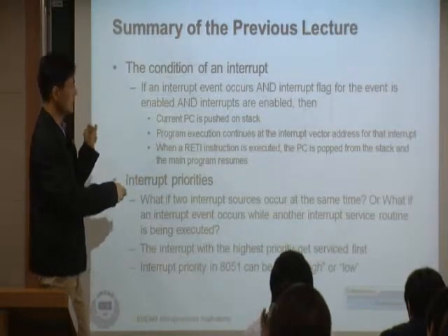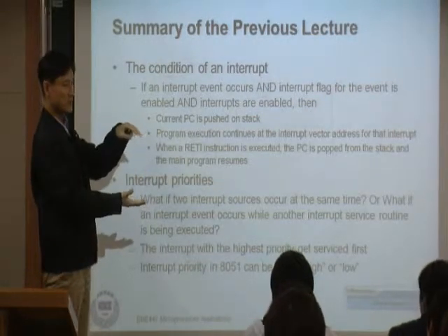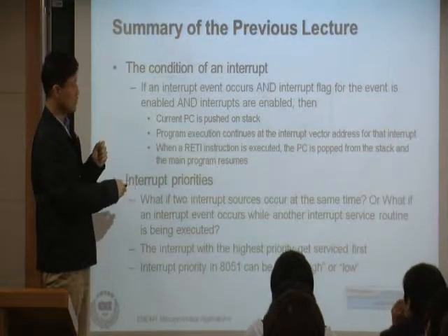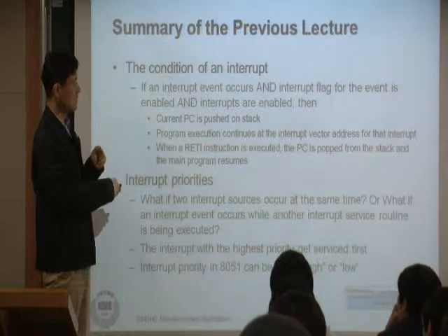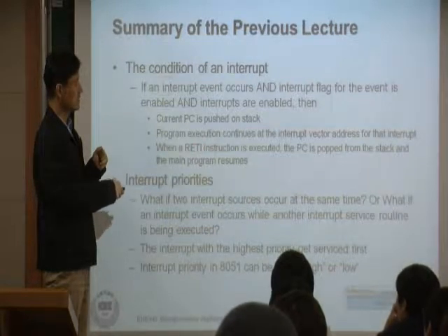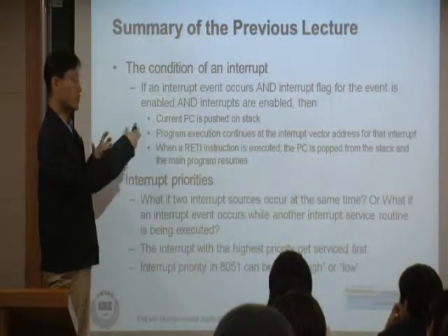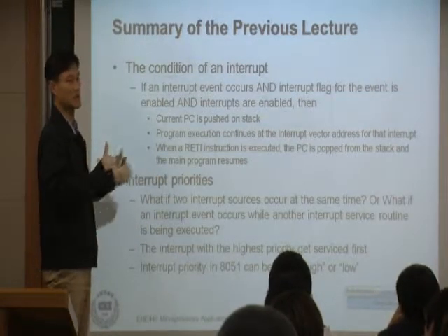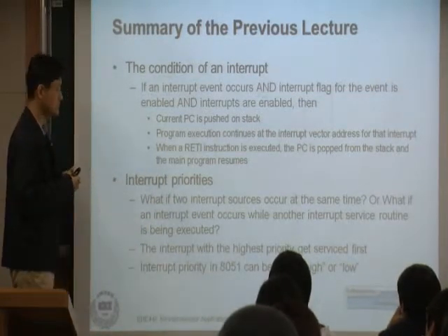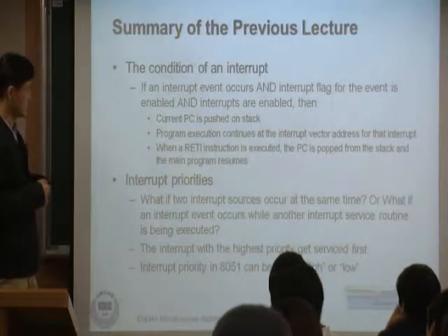That's another thing. And inside the interrupt service routine, at the end of the service routine, you have RETI. I means interrupt. So whenever the RETI instruction is executed, the program counter will be restored from the stack, and it's time to come back to the main program. Okay, so this is what's happening.